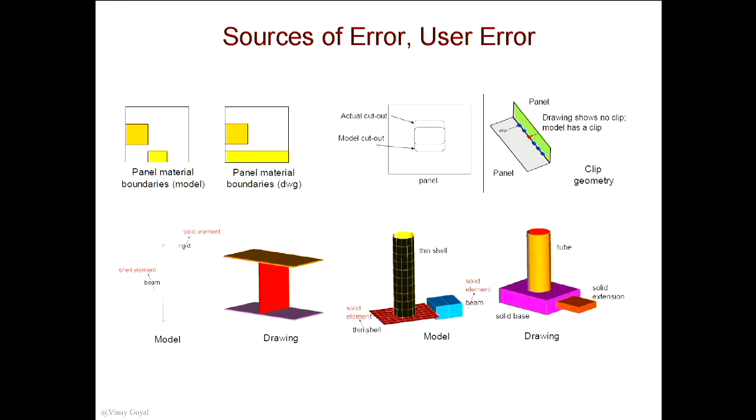Yeah, and then this is not a beam, right? This looks more like a plate, but that was represented as a beam here. And so be careful how you're representing things. They need to be representing reality. Remember, you're trying to idealize the physical structure with elements. And so you want those elements to accurately represent or model this physical structure. Okay.